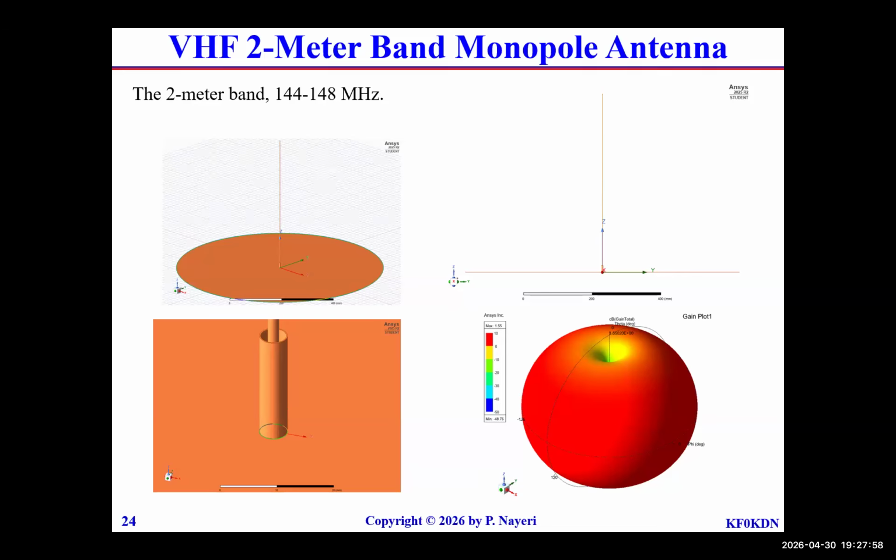So you do need something to act as your reflector back on this monopole for it to work, otherwise it won't. And you can test that in the lab. I mean, typically when you attach it to a radio, the radio body will act as the ground plane. Fair enough, not a perfect one, but it does something. If it doesn't, maybe you can have a small sheet connected to it and it would work.